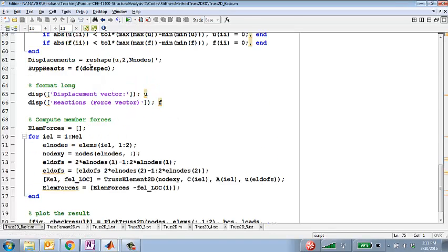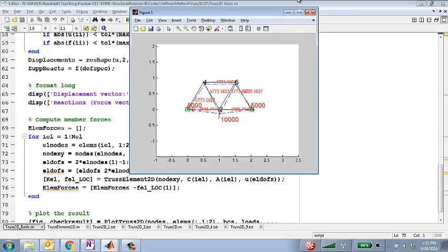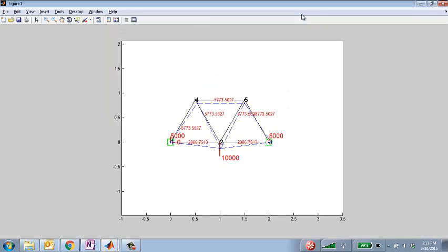The problem 2 that I just showed you, here there was a load, and instead of the load, if there is 0 load, and if I have a vertical settlement of one of the supports, what would the internal forces in the truss be? 0, because the truss would just rotate as a rigid body, right?